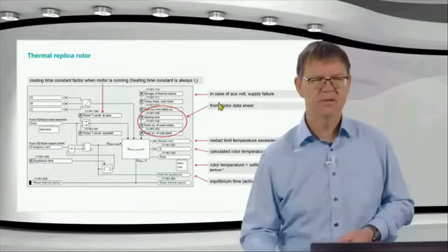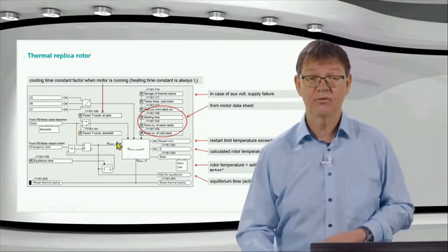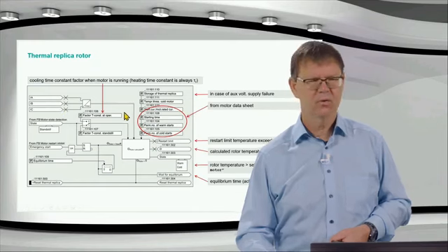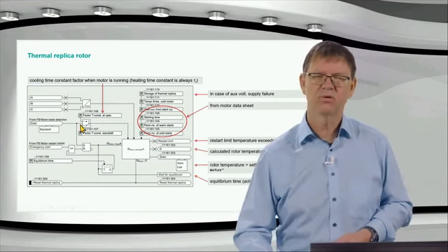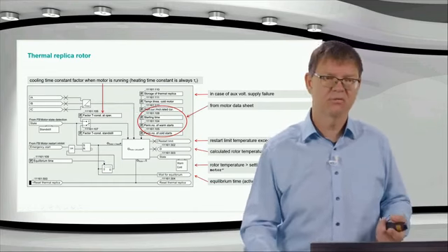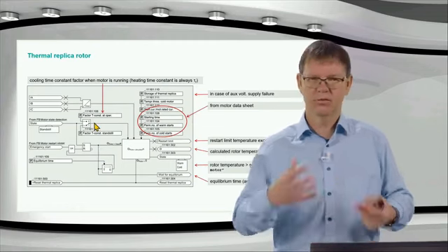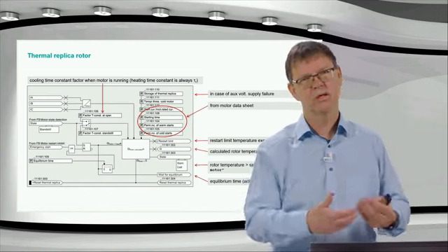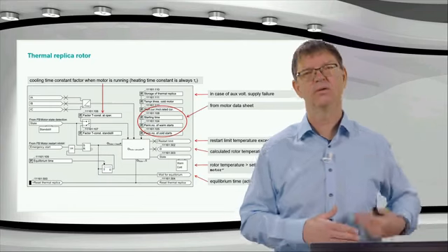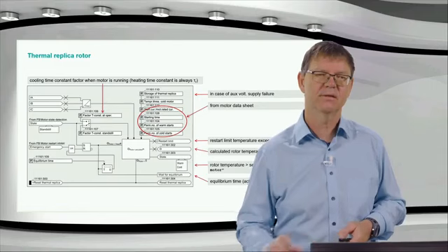The one is the cooling down factor when the motor is running. And then I have a cooling down factor when the motor is at standstill. So if there is no additional data from the motor manufacturer, then maybe you can leave that at the default setting. The default setting is 2. This is kind of additional security, just to wait, to give more time that the temperature goes down as compared with the temperature that rises when you start the motor. So when the current is there, the starting current is there.